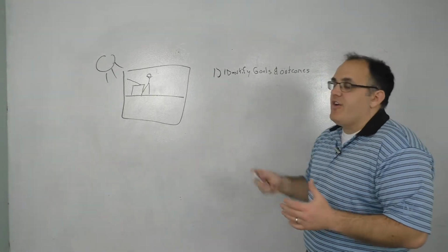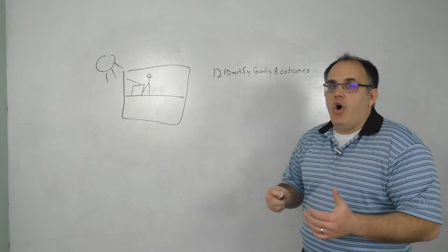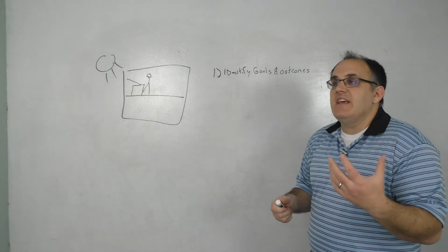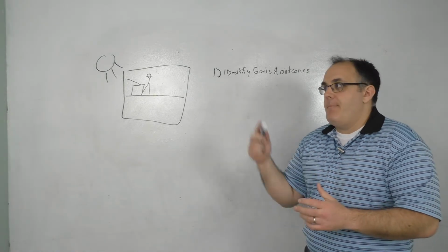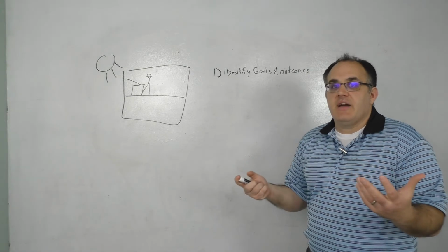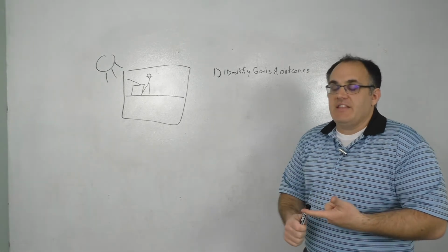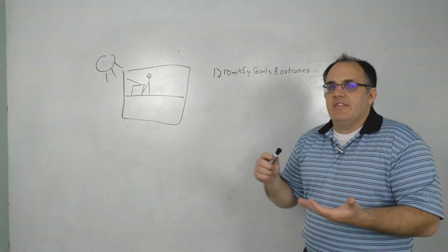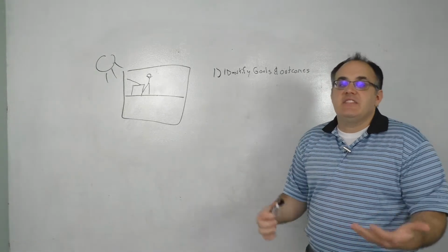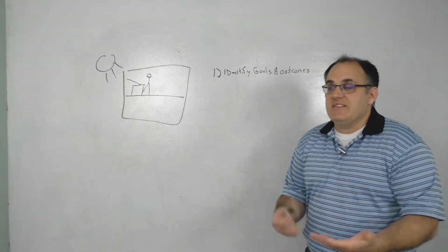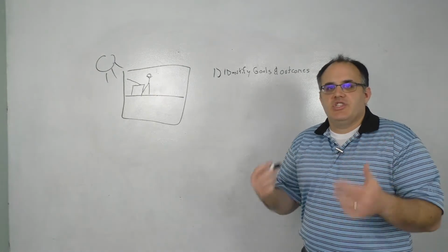For example, if our outcome is to improve tenant comfort, and we know that our goal is to measure temperature, that is different than if tenant comfort is defined by better chairs or by better lighting. Those may be how we achieve tenant comfort. However, if we know that our goal is increased temperature accuracy, then we know we need to validate that our temperature sensors are accurate, that our set points are accurate, that our flows for the spaces are properly designed for the loads. These are all things we take into account, versus if it's really just that tenants don't like the lighting in the space, then we change out the lighting. That's completely different.